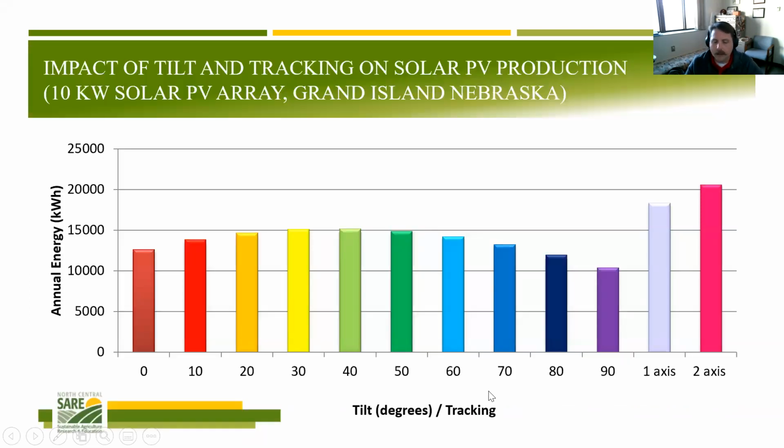All right, I'm about done here, but this is looking at it from just the tilt rather than from the azimuth. I'm assuming we're going to face these south, and you can see the tilt isn't all that sensitive. It's right up here, and if you're fairly close to that optimum, it's going to be okay as long as you're facing south. But really, this chart is about these two on the right.